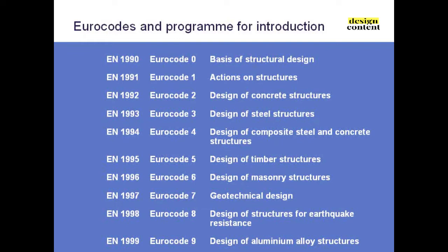And then the common ones, or most common material parts, are Eurocodes 2, 3 and 4, which we'll be covering over the next few days. But we've also got other parts. So there's a part for timber, part for masonry. Eurocode 7 we won't really be covering at all over the next 4 days. But there is a fairly significant change in geotechnical design because it moves over to ultimate limit state like all the other suite of Eurocodes, so it's fully compatible with concrete and steel.